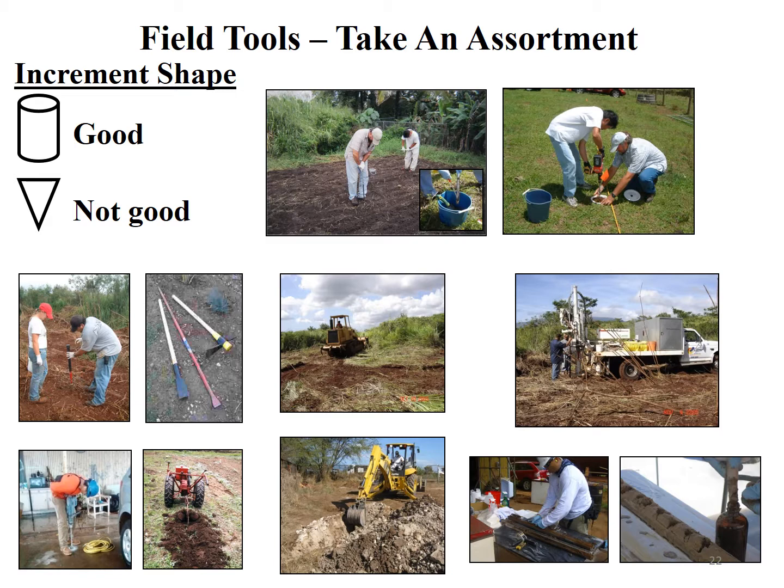Another point is to always expect the unexpected and take a variety of sampling tools in the field so you can ensure you get the job done, even if very dense, rocky soils are encountered. Test tools out on initial site reconnaissance, if at all possible, as I noted earlier. And it goes without saying, a superior tool for collecting correct increment cores will always save you time and labor.